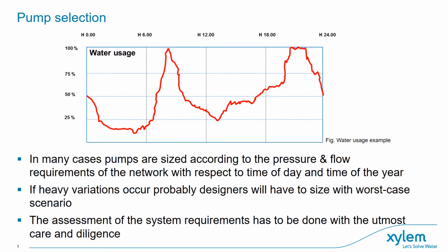So quite often there will be a constant pressure requirement with a variable flow, and we need to take into account any heavy variations where there may be peaks and troughs in that demand, so that we're evening out the operation of the pumps to ensure that the system requirements are met and we are operating the whole package at the most efficient level, so that we're not putting untold wear and tear on the mechanical equipment, and that it is working as efficiently as possible to ensure the maximum benefit of the electricity being used to power the pumps.